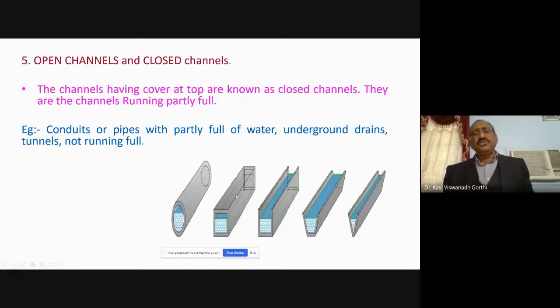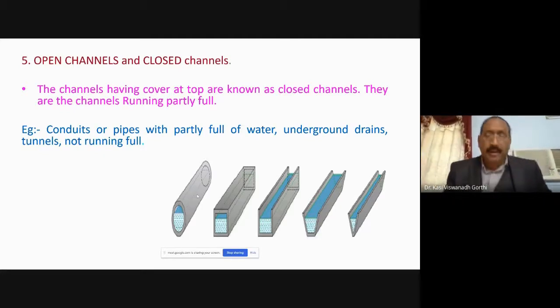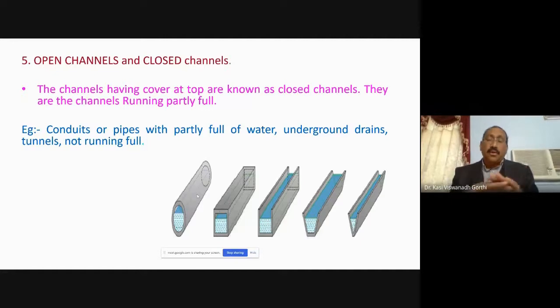Usually these closed channels, that means the top is covered, are used particularly when you have an underground drainage system, or sometimes tunnels which are provided. In such cases, we provide covered tops, particularly in the urban scenario, where the drainage cannot be left open to the atmosphere. Instead, all the drains will be covered. If the drain is completely covered, the top space may be used for parking, sometimes for a footpath,